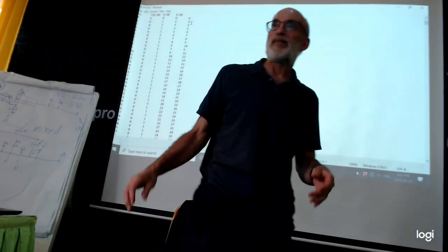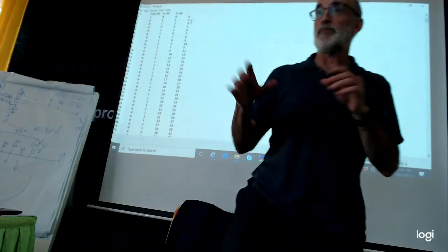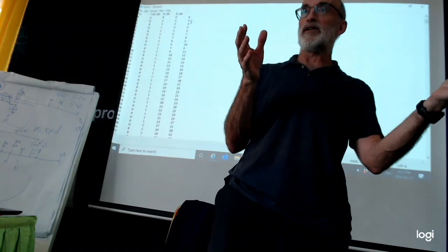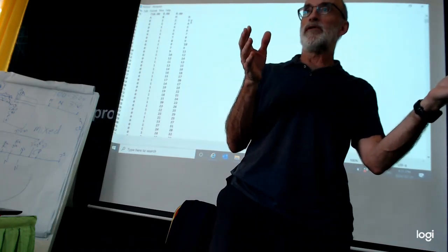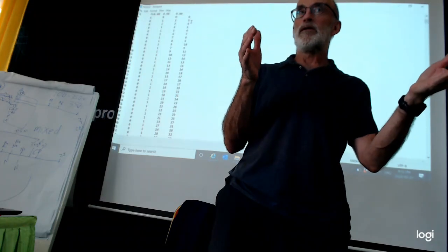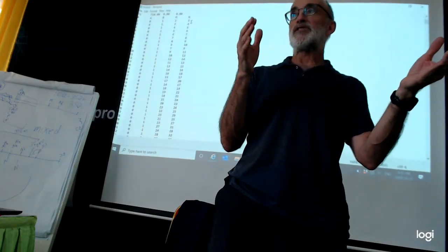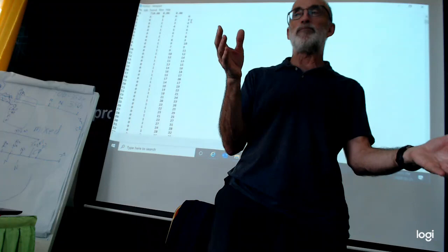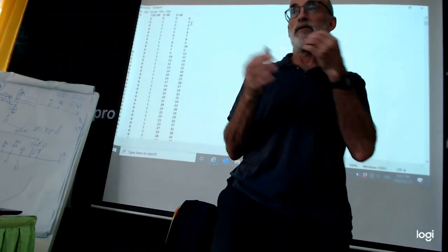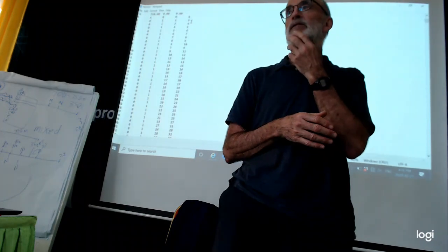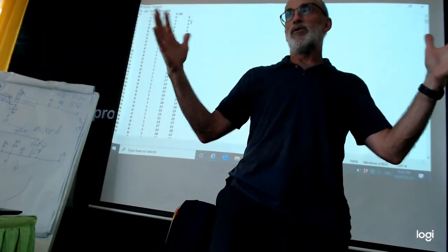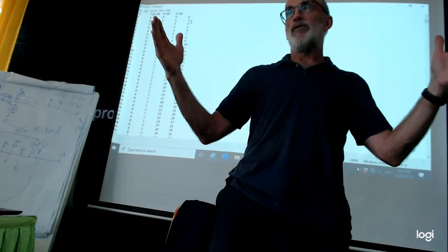Yeah. No, with any array, even dipole-dipole. Right? But you will see closer to the 1/4 side with the dipole-dipole. But your signal strengths might be weak and it might be poor quality data. The most reliable is a Wenner Schlumberger,